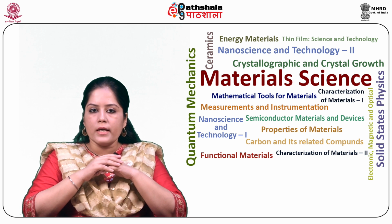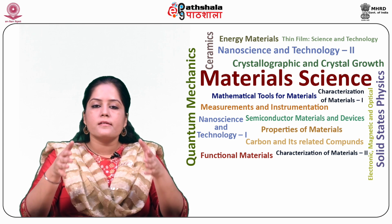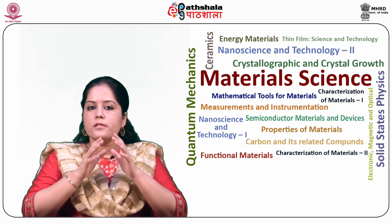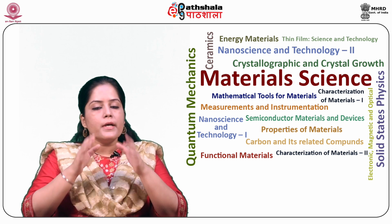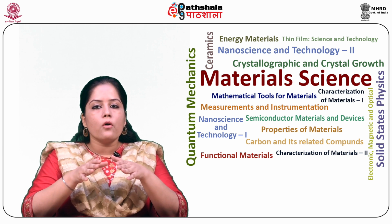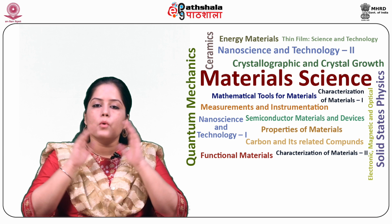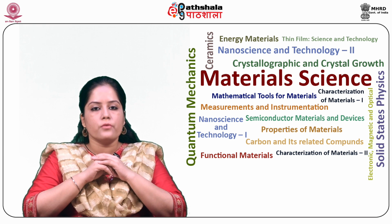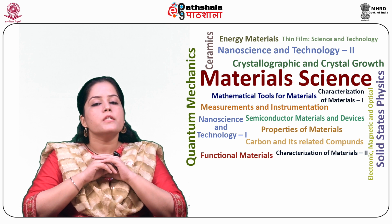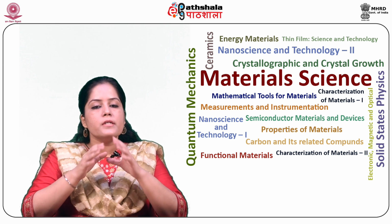One synchrotron storage ring can produce up to 20 beam lines that can be used in as many X-ray exposure tools. X-rays produced in synchrotrons are ideally suited for proximity lithography because they are naturally collimated. So rays produced in synchrotrons do not cause penumbras, and they produce deep resist profiles with vertical sidewalls and astonishing aspect ratios. In addition, because of the extremely short wavelength of X-rays, diffraction effects caused by the mask substrate gap in proximity printing are minimized.